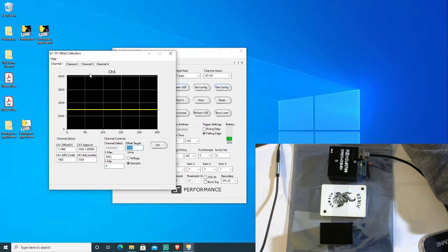And each data channel can also be individually configured for a different sensor. So a different sensor could be loaded on every single channel, and each of the 4 channels can be individually tuned with gain, DC offset, to get the most out of your sensor output, most out of your waveform. This is all in the continuous analog domain as well, so this is a control into the analog front end.